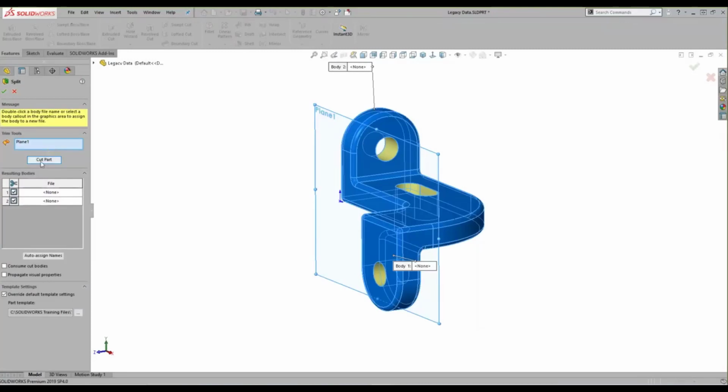You do need to cut the part so the software can calculate all the potential resulting bodies, but the actual selection boxes here in the resulting bodies window, that's what truly cuts it. So even if there were a possibility of creating 16 bodies, I could choose it in a way that only creates 6 bodies, for example, or 8 bodies or something like that.